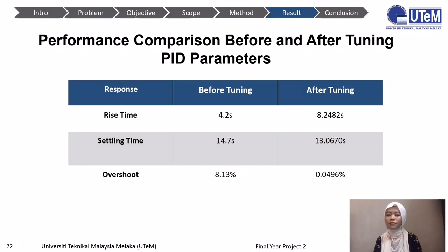The rise time after tuning is much slower compared to before tuning, as we set the response time to slow. The settling time is faster than before tuning, and the percentage overshoot after tuning is 0.0496%, which is much lower than before tuning, which has 8.13%.